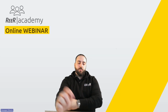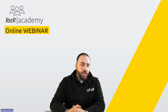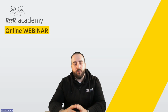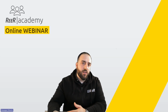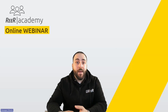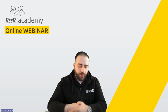Is it already possible to connect safety mats with resistor? Let me tell you this. For the safety mats, we are able to detect the electromechanical contacts, not the impedance value. So we are not able to manage that kind of signal. We are working on a particular module able to manage that kind of signal, and I hope it will arrive in the next year.